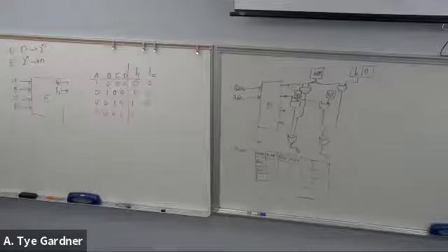Now, in the case of both encoding and decoding, your output F could be stored as binary, as I've written it here, or gray code, right? So gray code being the counting process wherein only 1 bit changes at a time, right? That's what we did with K-maps, right? Where we were utilizing gray code to ensure logic adjacency.